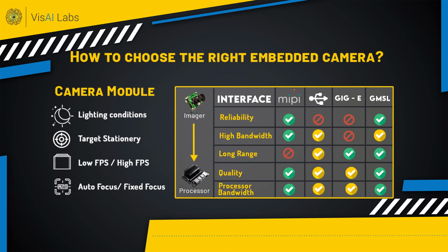USB, we can go for a longer cable, of course, but it also has a limitation of bandwidth. But USB has fair enough bandwidth for full HD 60 frames per second. So if you are looking for a POC with a decent camera, then probably USB 3.0 would be a better choice compared to other interfaces. It has decent reliability, it can also support high bandwidth, and you can go for 3 meters or 5 meters. Also, it can support both YUV and MJPEG.